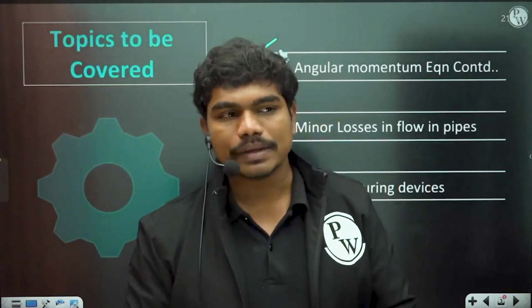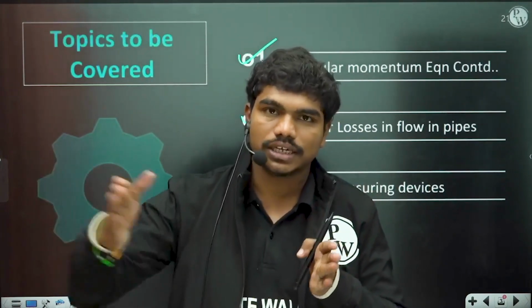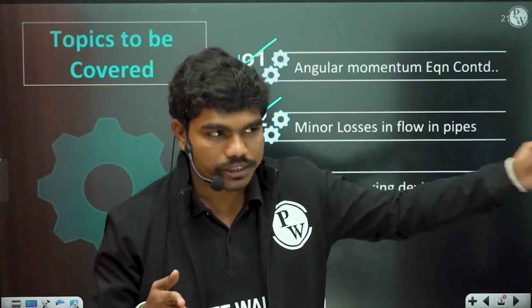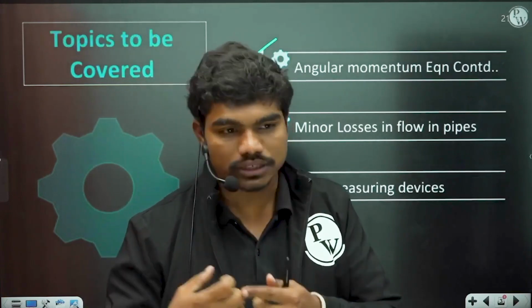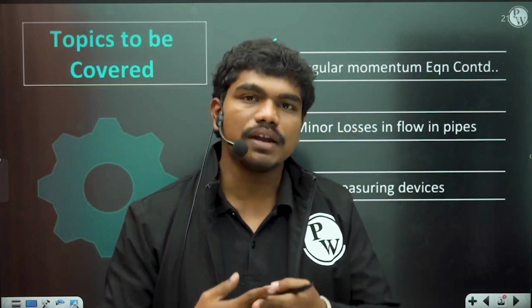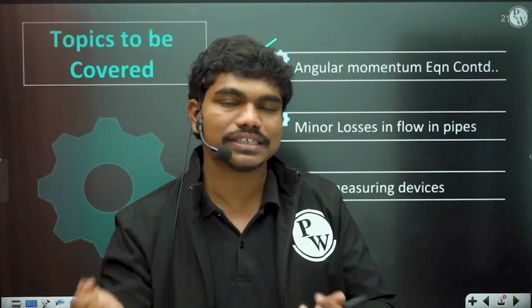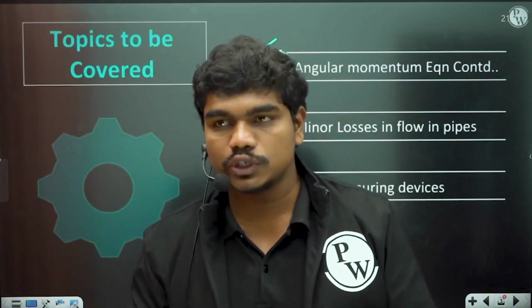Whenever you want to transport fluids to a large distance, for example in oil companies, when I worked with HPCL, we had a pipeline of around 700 kilometers length. In such a long pipeline, there is certain pressure drop that happens. To compensate the pressure drop, because if the fluid has to flow there should be enough pressure, normally every 50 to 100 kilometers we will keep one booster pump location. The fluid enters the pump and it again increases the pressure of the fluid. So the main reason is this pressure loss due to friction.